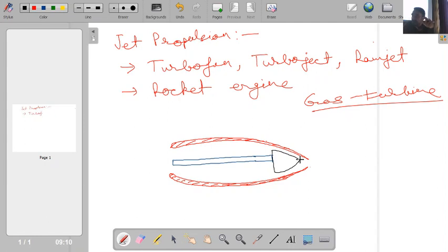One, isentropic compression, then constant pressure heat addition, which is nothing but a replica of a combustion process, and then we have isentropic expansion. After that, in the actual cycle, exhaust gases are just sent to the atmosphere, whereas in case of a thermodynamic closed cycle, these are brought to the initial state by extracting heat from them at constant pressure conditions. So this is nothing but an ideal Brayton cycle. So the ideal Brayton cycle is used in gas turbine engines.